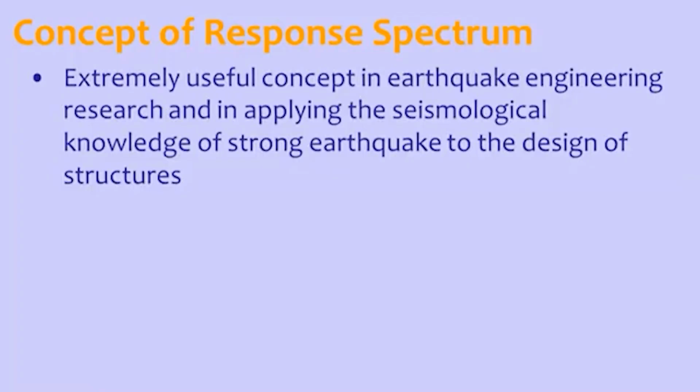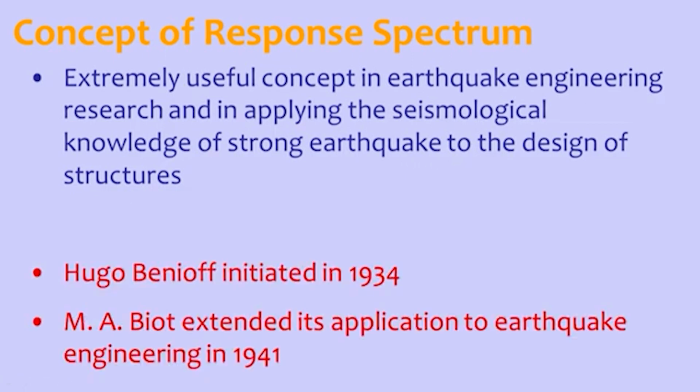So, the concept of response spectrum says that if we know the natural period of the building, the maximum response of that building to a given component of earthquake can be known from the response spectrum concept. This response spectrum is an extremely useful concept in earthquake engineering research and in applying seismological knowledge of strong earthquake ground motion to the design of structures. It was first proposed by Hugo Benioff in 1934, and Biot extended its application to earthquake engineering in 1941.